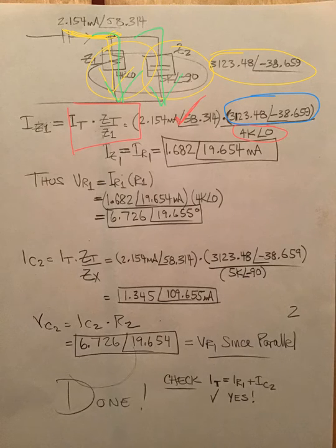In blue, this ZT is not the total. What I need over here in the blue circle is a sliver of ZT that came from the parallel circuit. Remember, current divider can only be used on a parallel circuit or a sliver of a series parallel circuit where there is a parallel section.